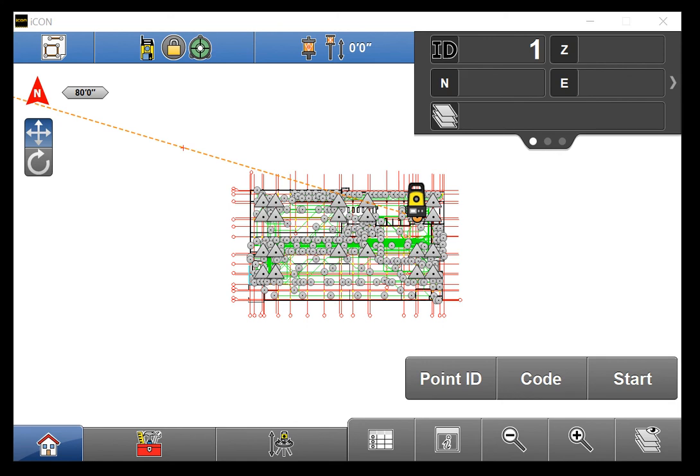So, if an as-built drawing is a drawing that represents the exact locations of constructed elements, then the as-built software is a program that allows us to digitally draw the as-built drawing. We can achieve this by recording exact points on the surfaces of the elements, or offsets to those surfaces, and by giving the points specific descriptions that can be deciphered later by the person doing the drawing in CAD or Revit. They can connect the points stored with lines that outline the surfaces, or they can draw exact dimensions from those points to grid lines, control lines, or other features of the project representing the exact locations of the elements. This reduces the need for hand-sketched field as-builts.